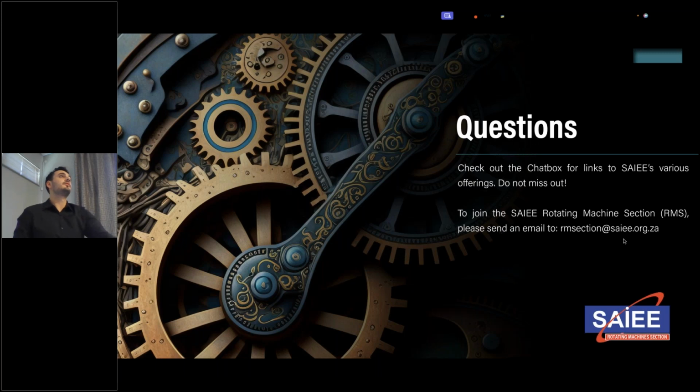So not necessarily in the PMSG. I think a better solution for the PMSG is the shifting of the permanent magnets, not this process of changing the slot dimensions. I think that would be the way to go for using PMSGs in wind turbines.